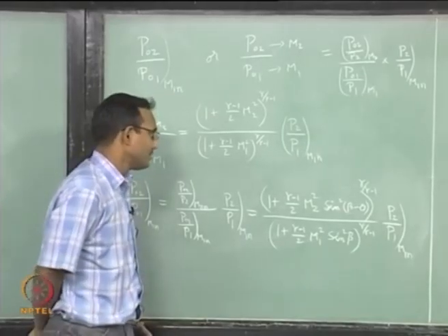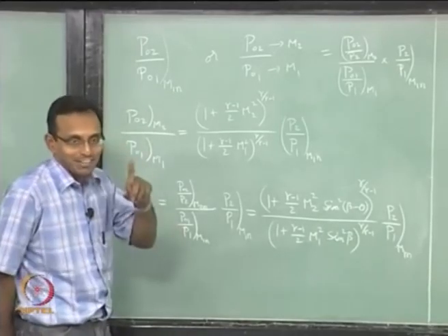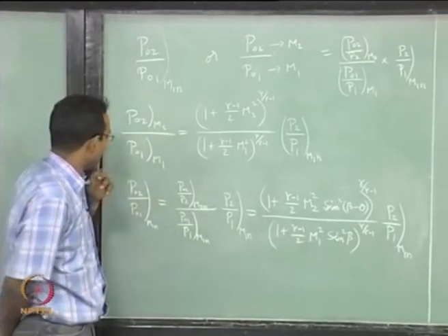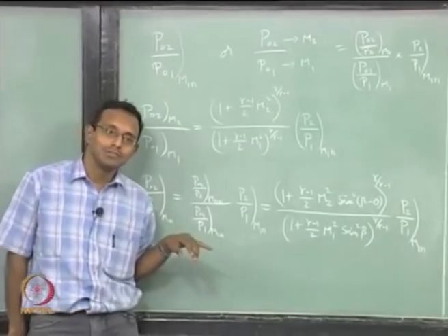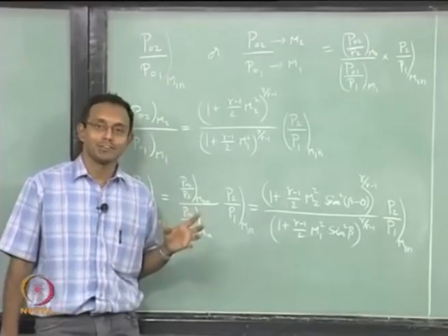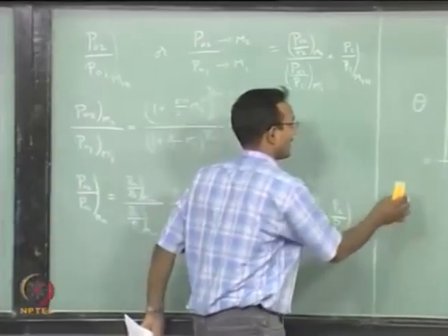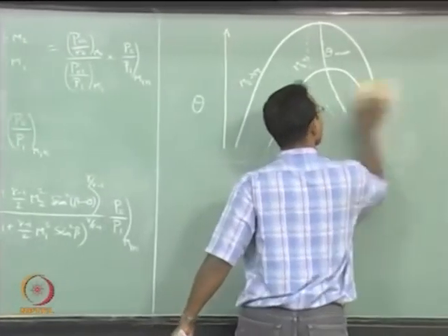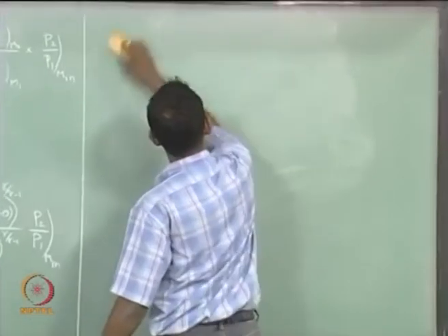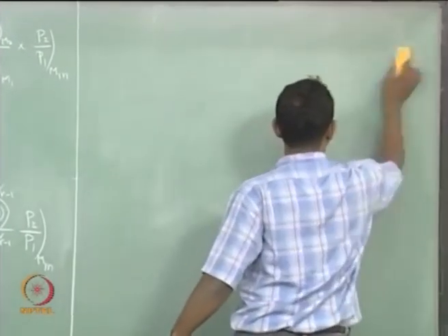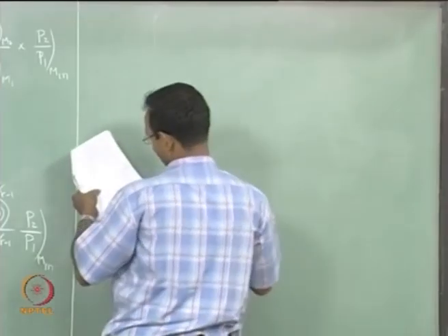So, in my opinion you should not be using this, but wait, we said P naught 2 by P naught 1 is related to entropy jump across shock, right. We had this formula, I will go back and write that again. I wanted to confuse you a little bit, so I am taking you this particular path so that you will be more clear at the end of it.